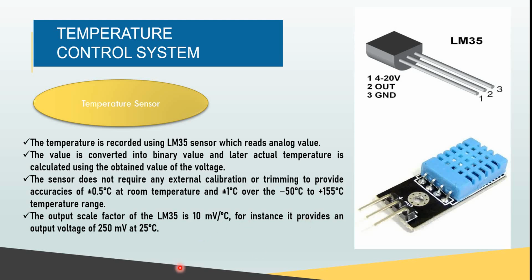For instance, it provides an output voltage of 250 millivolts at 25 degrees Celsius. For 1 degree Celsius, 10 millivolts. For 25 degrees Celsius, 250 millivolts. Okay.